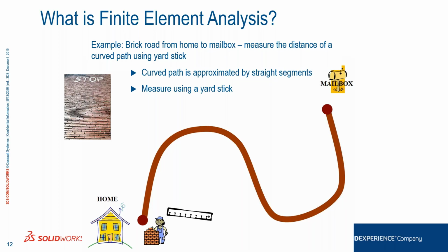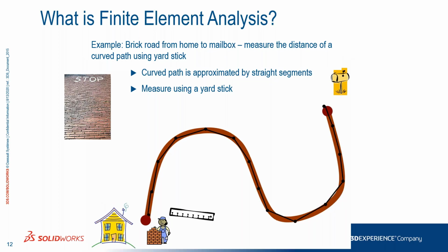I have to break it down into small elements like this, put the scale like this, and measure the complete length of the rope. Finite element analysis works in a similar way. We break the complete model into small elements interconnected by nodes, and we calculate the stresses, strains, and displacements on those elements.